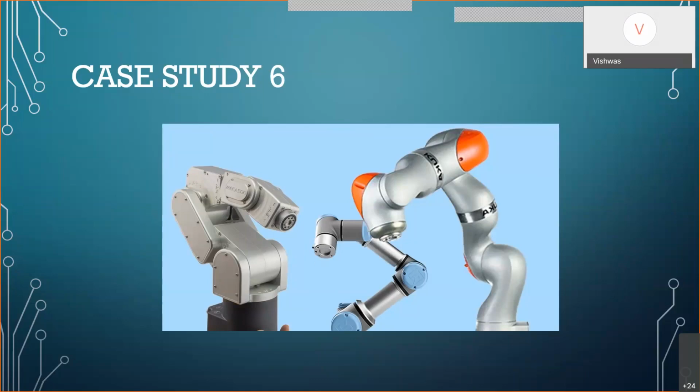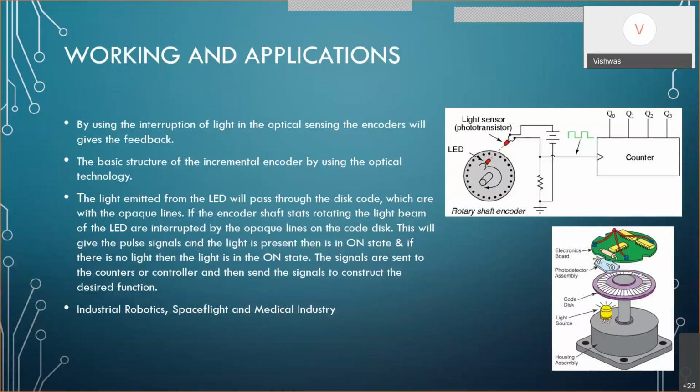In order to sense the location or the angle of each individual joint, we need something called encoders. Here we are talking about rotary encoders. I'll go to the next slide. There are multiple technologies for rotary encoders, such as magnetic-based ones, which calculate in terms of movements of magnets. For digital electronics, here I'm choosing the rotary encoder with optical input.